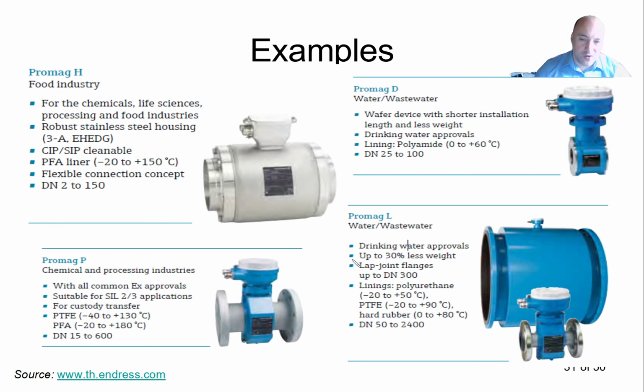It requires a conductive liquid. So if you are designing an application with those sensors, you first need to make a list of properties of your liquid, so that you're able to find if this principle is suitable or if it's not. In terms of temperature range, it is approximately the same as for the ultrasonic. You can see here it actually depends on the material of the liner that insulates that. So if it's PTFE, for example, which is Teflon,